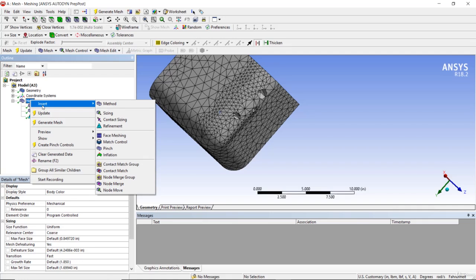With whatever options that you have learnt, let us say the global settings as well as the local settings, you will be able to efficiently create meshes for a number of problems. But if you want to create meshes for very high-end geometries, then you are going to need to learn how to generate efficient meshes and other advanced options, which are a course unto themselves. In the next lecture, I am going to tell you about the different mesh metric systems that are used to quantify the quality of the mesh generated on the geometric body, and we are also going to see where we can access those options inside Ansys Workbench.